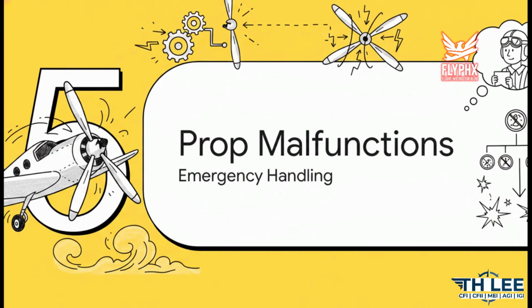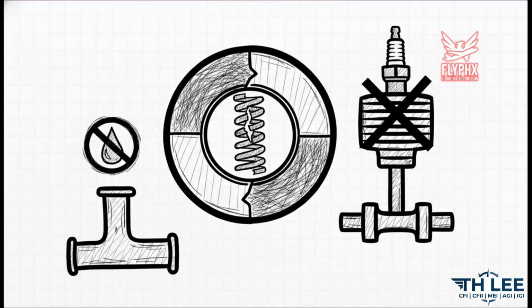Section 5. Handling propeller malfunctions. A good aviator is always prepared for the unexpected. So how does this mechanical system behave when things actually go wrong up there? Well, if you lose engine oil pressure, the propeller hub empties out. Without oil pressure fighting it, that spring inside the hub immediately snaps the blades to full low pitch. This will result in a dangerous engine overspeed condition. On the flip side, what if the speeder spring inside the governor breaks? All tension is gone, the pilot valve slides up, oil floods the hub, and forces the prop to a high pitch, giving you a very low engine speed.